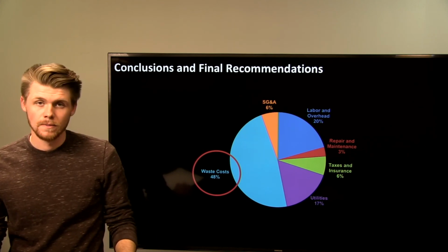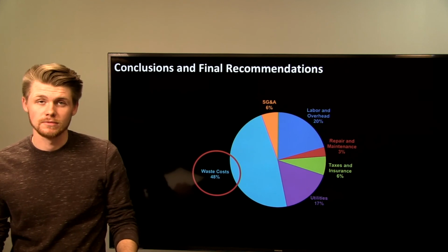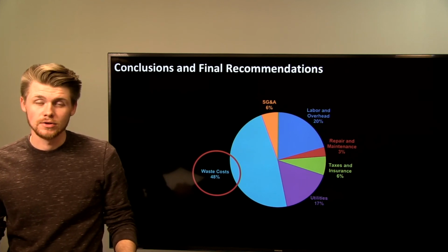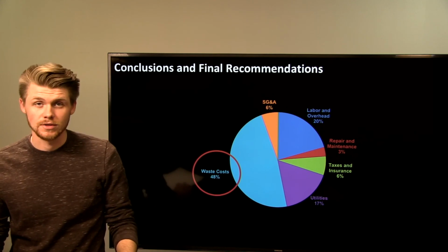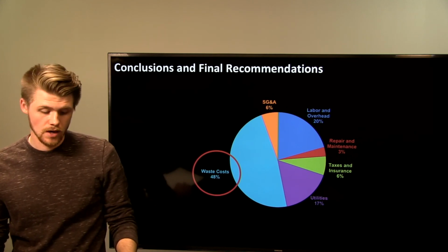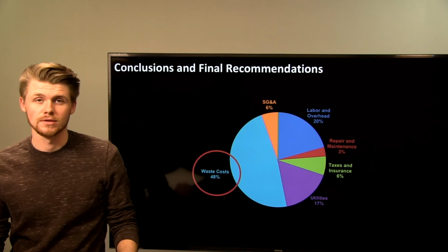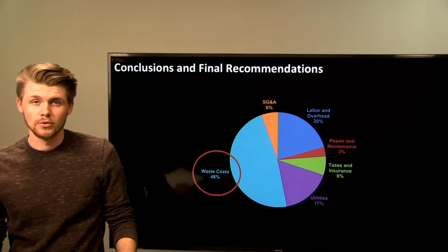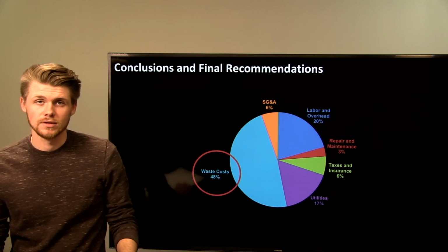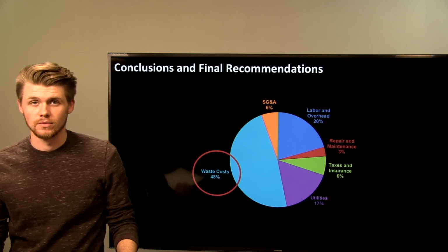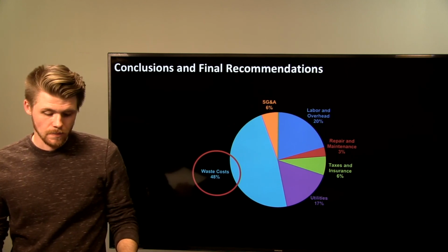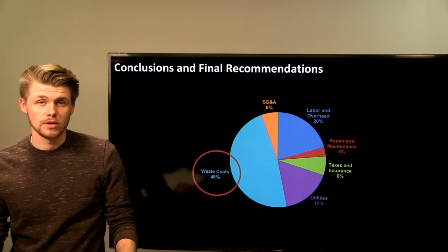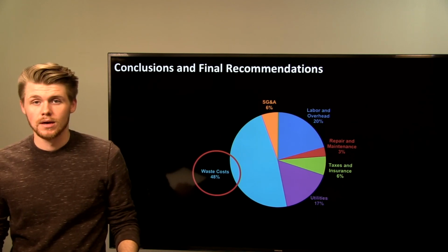As proved in the alternative study slides before this, sodium bicarbonate could be used as a very useful thing to neutralize acetic acid, so you don't have to purchase a stainless steel distillation tower. But as proved in the alternative study, it's saving on the capital cost, but the $1.3 million per year generated from the acetic acid stream is a pretty good revenue for our company, so we decided to go against it and leave it in. Our final recommendation would be to go ahead and build the plant.